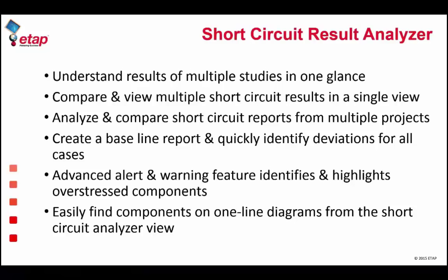The purpose for a result analyzer is to essentially understand the results from multiple studies in one summarized table. So when you're trying to run various scenarios, whether they are for load flow or arc flash or short circuit, we obviously get multiple sets of results from these different cases or different scenarios. And the analyzer allows us to take these multiple cases, put them into a single view, and then compare.